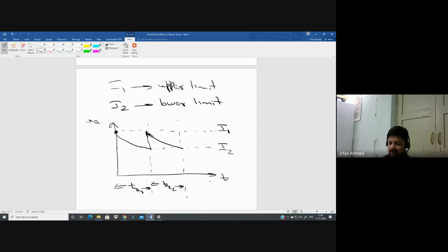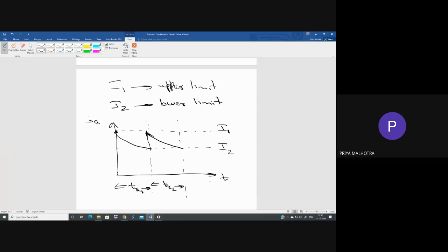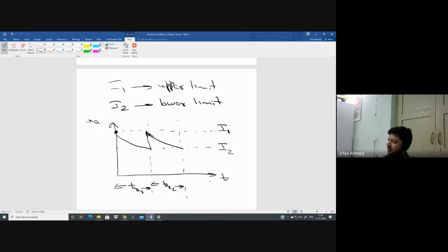Similarly, in the case of your induction motor, it is up to you how much torque you want to give, and your motor must be able to handle that much torque, current, all those things. You are adding external resistance, so all these will matter. You want to reduce the starting current below the full load current of the motor? I don't think you'll ever have starting current below the full load current. If you have that, I don't think your motor will start.